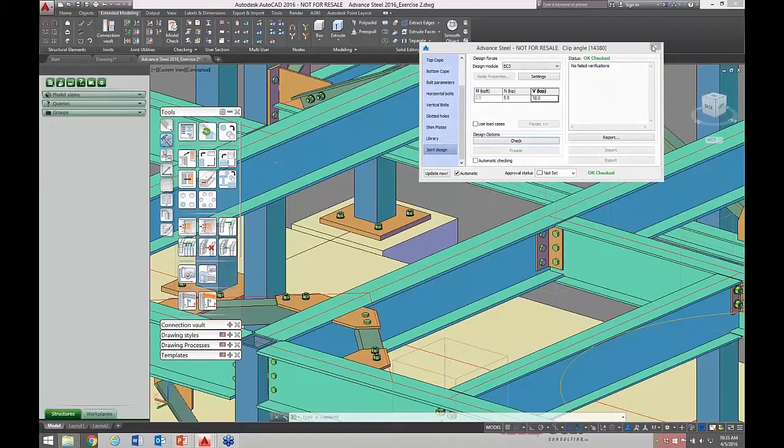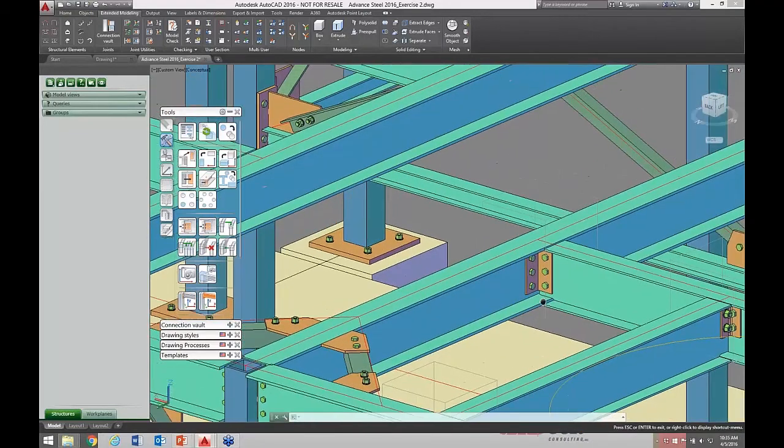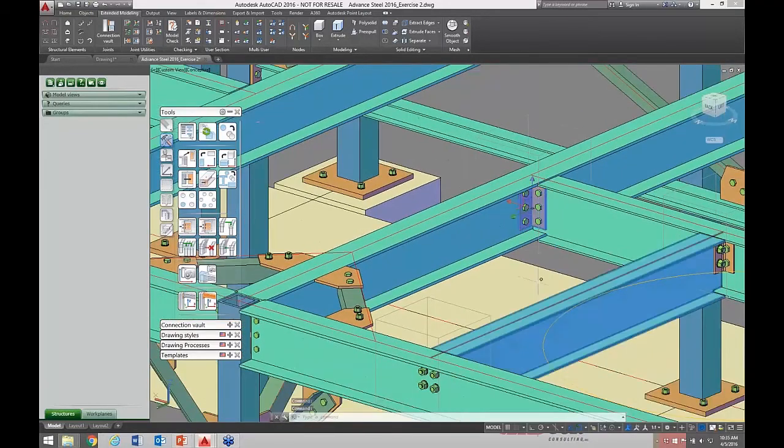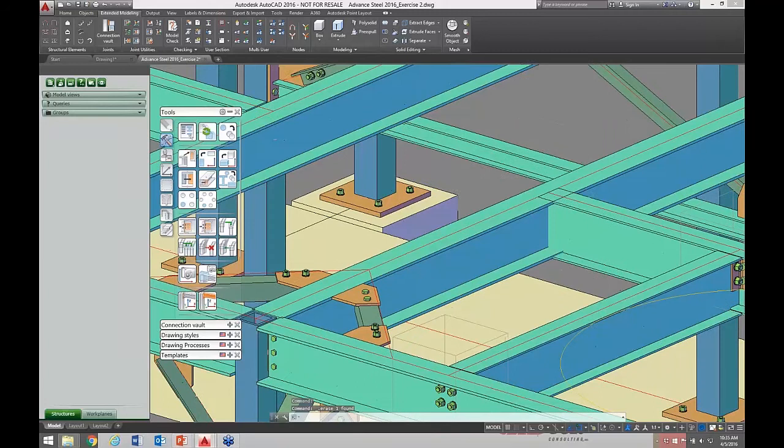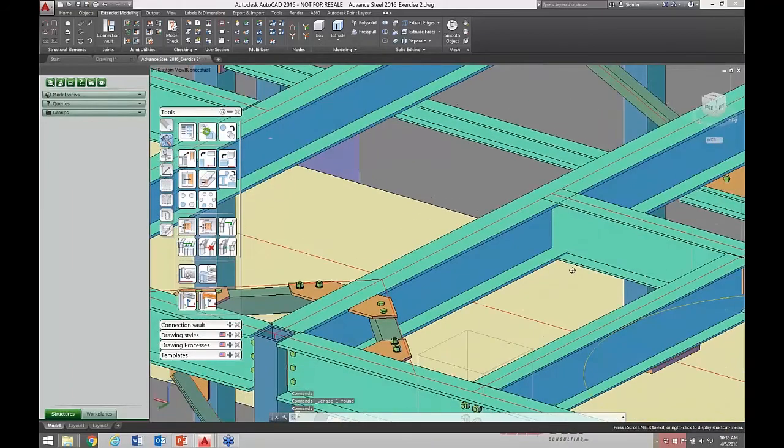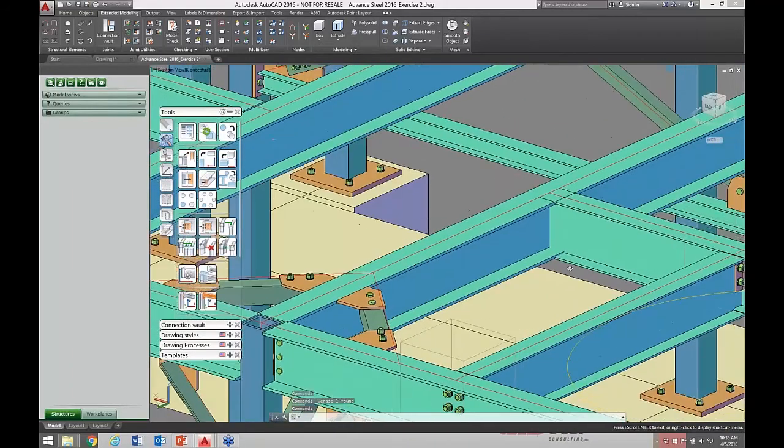As far as clash detection goes, and the fact that I actually applied all of these connections, I'm not going to have any clashes, I would hope, as long as something didn't fail on me somewhere. So let me delete one of my connections by selecting one part and hitting the delete key. And you'll see very visibly, I've got a collision right here, just by virtue of how we began modeling. It's not applying coping. There aren't any setbacks or offsets at this point.